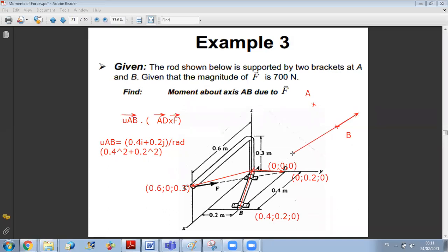Because look, if I take any point here, when you do R vectorial F, by definition, let's say you consider this position vector R. So if you do AC vectorial F, or if I take another point from the other side, so this is C and this is D. If you do AC vectorial F, by definition, the vectorial product is in magnitude equal to the magnitude of AC times the magnitude of F times the sine of the angle in between. When I consider AC and F, what is the angle in between? It is this angle. When you say F times AC sine theta,